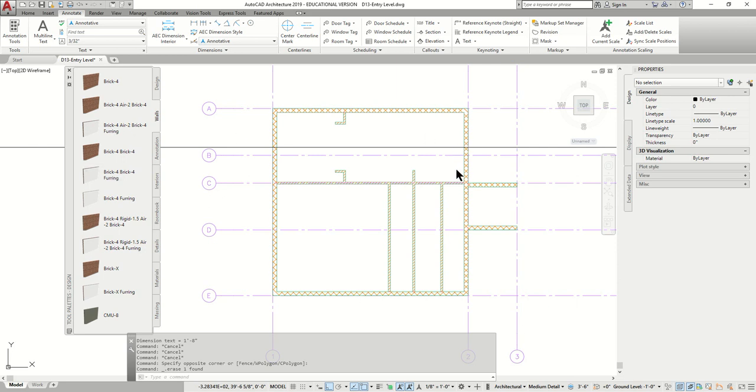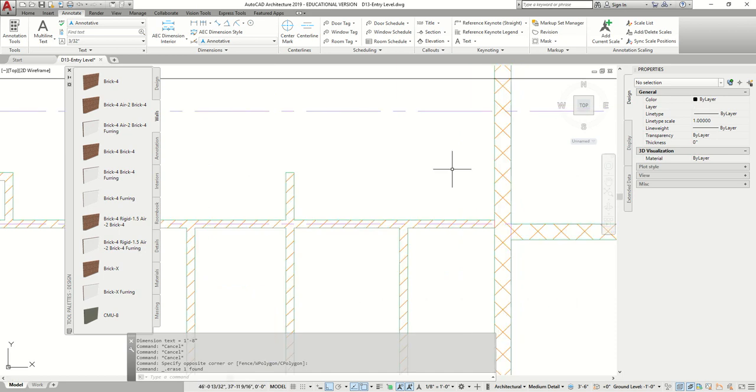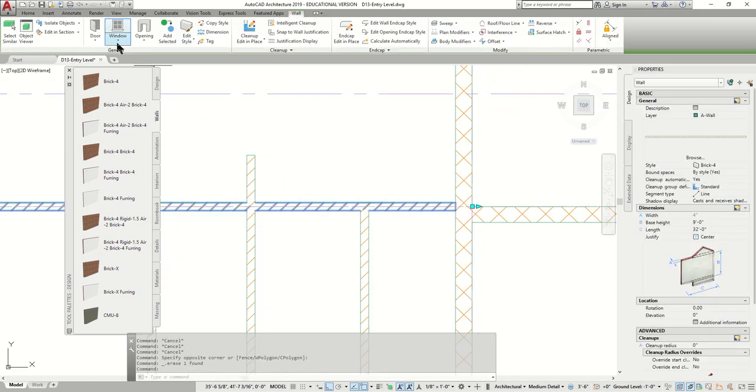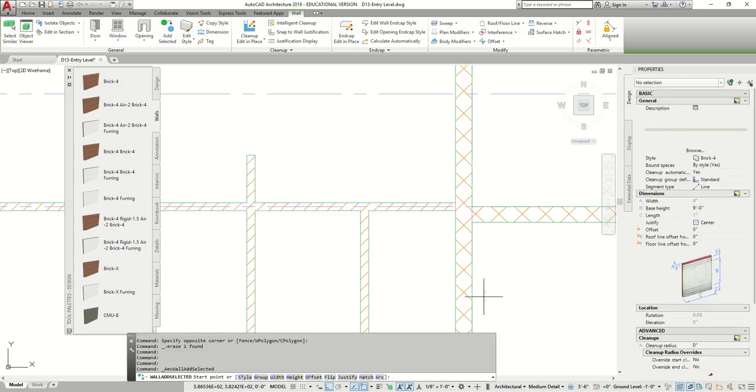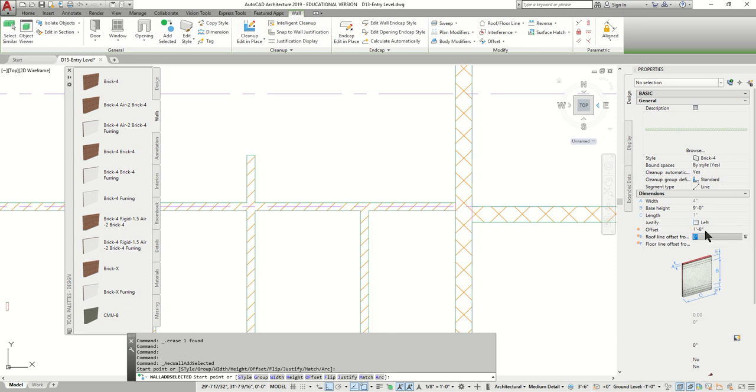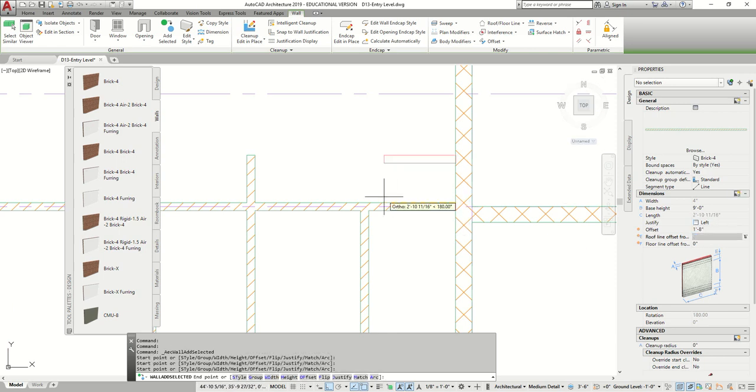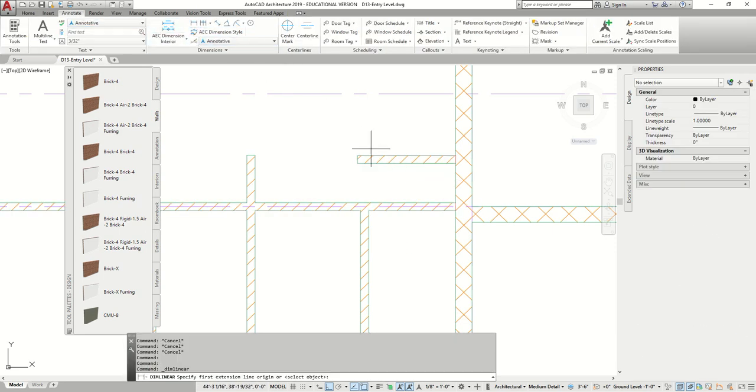We're going to add the one on top here, right up here first, which should be right above here. So we're going to go this wall again, add selected, offset of 1'8". Yeah, offset. So let's go from the left side, offset 1'8". From here, we're going to go 3'11" -7/16. There's one. If I go check the distance between them, this should be 1'8".